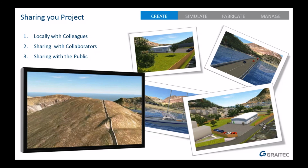One option that is a good option for you guys is Navisworks. Bung all the InfraWorks stuff into Navisworks, and then you can link to Navisworks in Revit as well, can't you? So that's another option. I think the biggest problem is people who use Revit tend to want to use it for everything. And we can't do that because Revit doesn't work on the British National Grid. It doesn't work with the size of data sets that we work with. It's designed for a different function than the civil engineering side of things. So we do have to be careful with that.